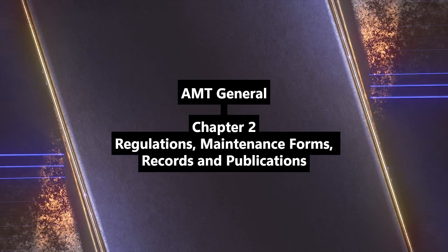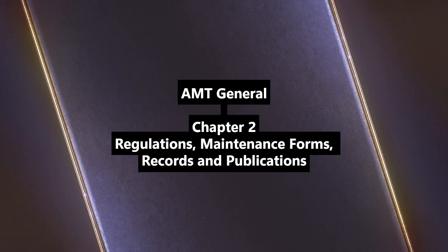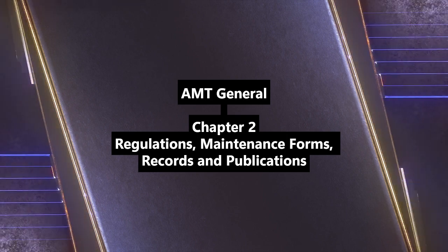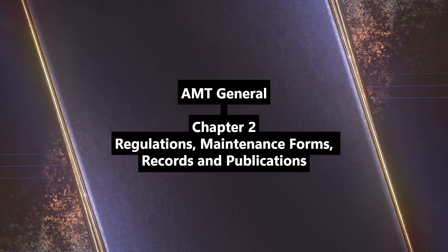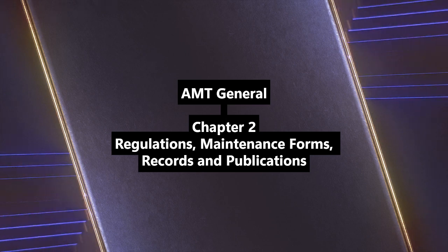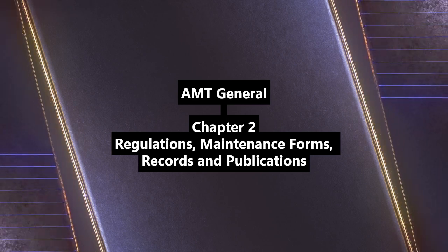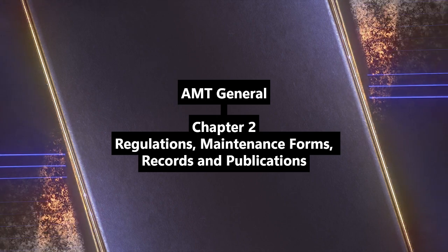Now, a serious issue. Suspected unapproved parts. It's very serious. Our source breaks parts into 4 categories. Good parts, good paperwork. Good parts, bad paperwork. Bad parts, good paperwork. And bad parts, bad paperwork. Exactly. Only Category 1 is acceptable. Categories 2 and 3 are SUPs. Right. Good parts with bad paperwork, or bad parts possibly masked by fake paperwork. Technicians need to be vigilant.